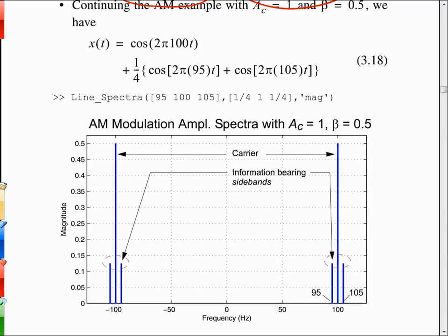We have the 100 hertz, in this case, which was the carrier frequency. For KRDO, that would be replaced by 850 kilohertz. And then the single tone message at 5 hertz, which would not really be audible, we'd raise it up to some higher frequencies or just have a message signal on there that would fill the spectrum in more rather than just spectral lines. But at any rate, in this case, we have something at 105 and 95, and then the same matching set at the negative frequencies.